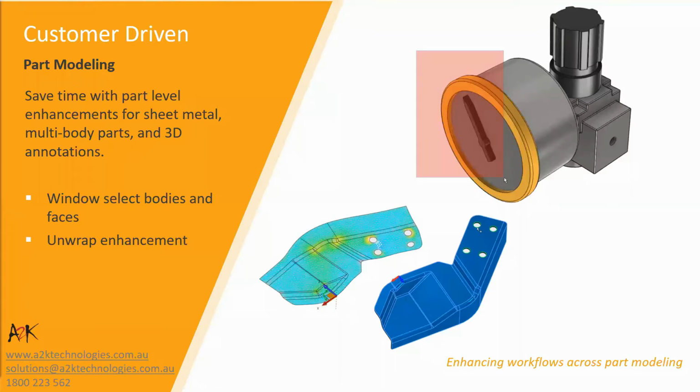So I mentioned you can now window select multiple solids within a multi-solid part, an IPT file, by setting the appropriate selection filter. This sets the selection filter to bodies to window select or crossing window to select multiple bodies. You can set the selection filter to faces and edges to window select multiple faces and edges, or cross window select multiple faces and edges.